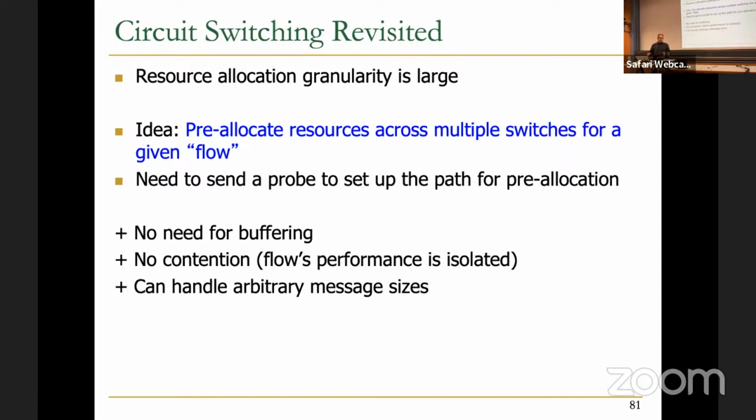That being said, usually you add buffers because you don't want to have a long combinational path to the destination, because a combinational circuit is noisy, and also the frequency of this circuit might be low. So people add some buffers in between in order to break that combinational circuit.